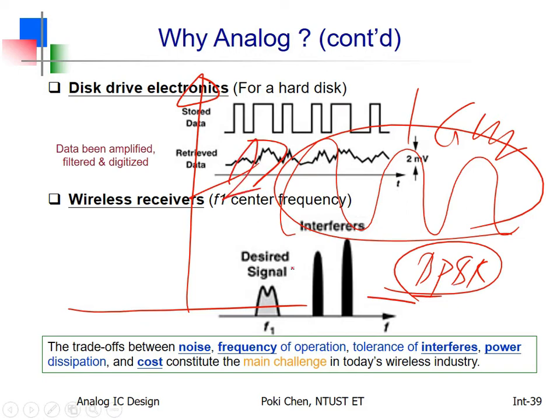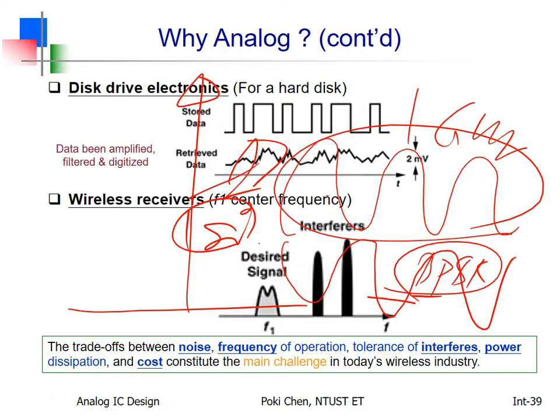And for the other one, the phase is 180 degrees in difference. That is for BPSK. One is in phase, the other one is out of phase. Something like this. So the signal itself is still sine wave, pure analog, but how to carry the digital information? With different phases.